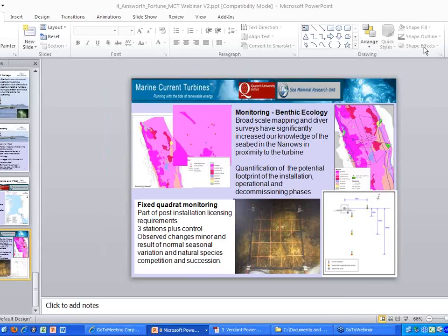Right, well, the turbine, we actually have a pitch control system on the device. So the first thing we do is we drive the blades to neutral drive, so it doesn't actually extract any energy. And then the speed just naturally drops, and when it gets to a speed around 2 or 3 RPM, we can start applying the disc brake to actually slow it down further. So we can actually go from full speed to completely brake speed in a matter of seconds, which is very, very quick. And no, repeated braking doesn't damage the structure.